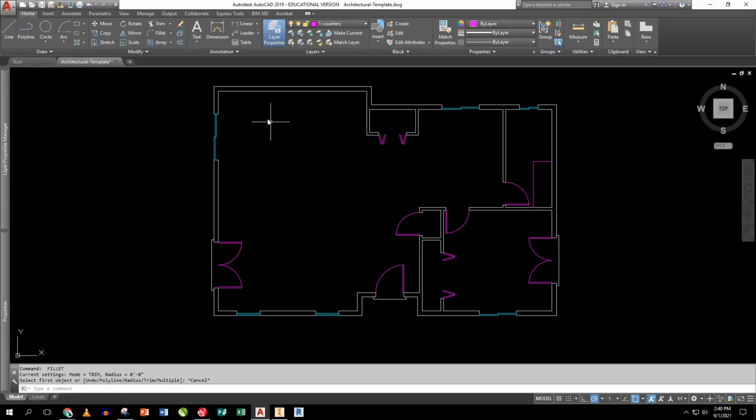Now, looking at this, because I know what this is, it would have counters out here. I do them the same way I did this. I can honestly do it with just an offset command of 24 inches from here out this way and from here out this way. And then I just need to know how far out from the end of this it sticks, if it sticks out from there at all. And in this case, it sticks out about 4 feet. So I just offset 48 inches from here down. I can now erase this and do a line right here down to there.